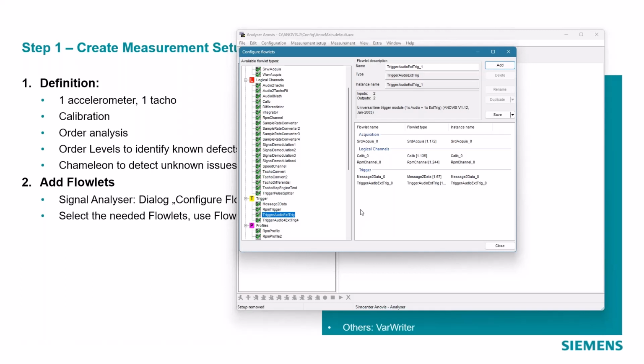For example, we can provide an RPM trigger. That means we can start the analysis if the device under test starts to turn at 1000 RPM. And then let's assume the motor ramps up to 5000 RPM, then we can stop at 5000 RPM. And we do this exactly always with every measurement at the same point so that we can produce reproducible data. So therefore we use triggers.